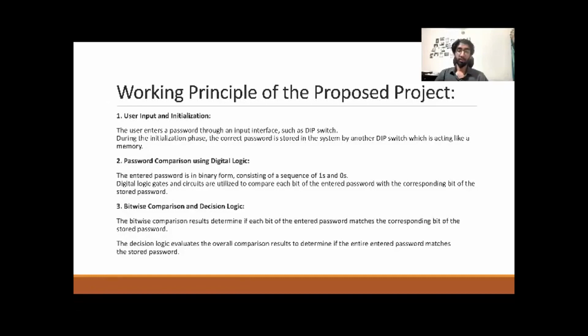Thank you, Jahid Antor. Myself, Ghulam Kibriya Himel, Department of Computer Science and Engineering. Now I am talking about the working principle of our project. User input and initialization. The user enters a password through an input interface such as a DIP switch. During the initialization phase, the current password is stored in the system using another DIP switch, which acts like a memory. Password comparison using digital logic.